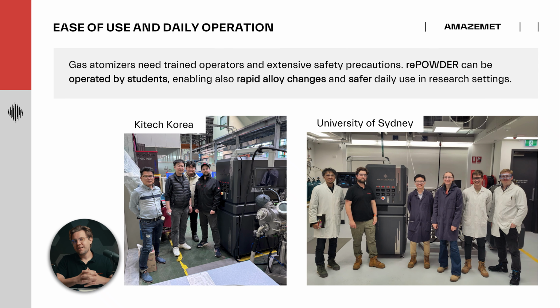Talking about scale, it's also about ease of operation. Gas atomizers are usually large industrial facilities. Those require skilled personnel not to blow it up. We are using a lot of supersonic gas and explosive materials are being created, and it requires a lot of skill not to harm the device itself or the personnel.